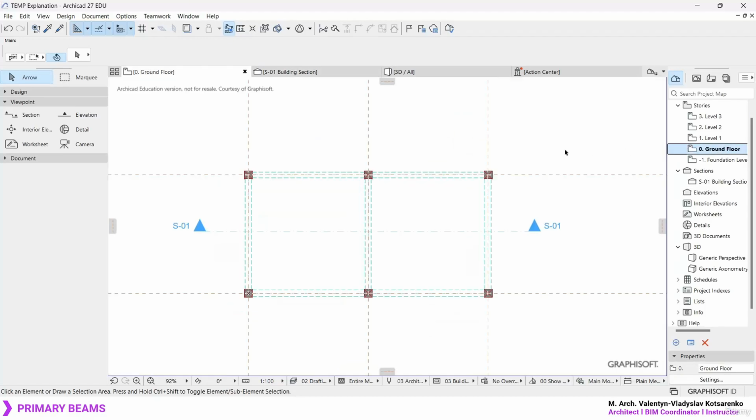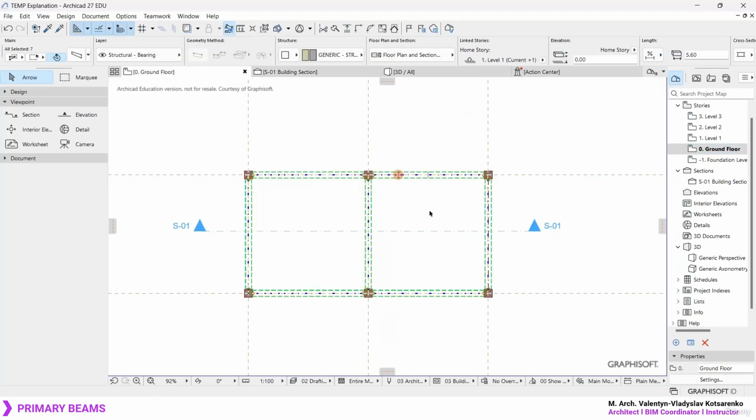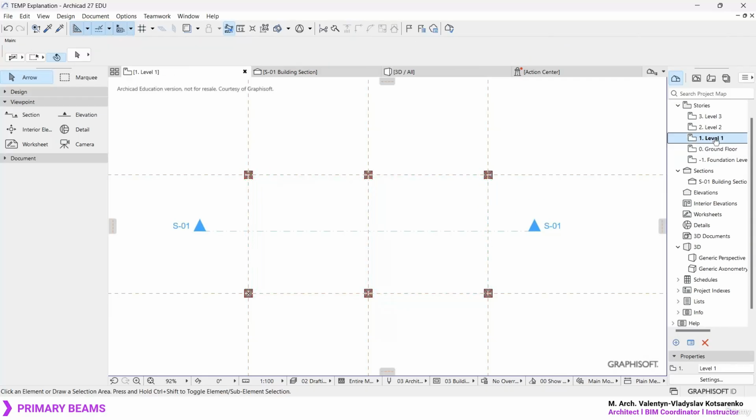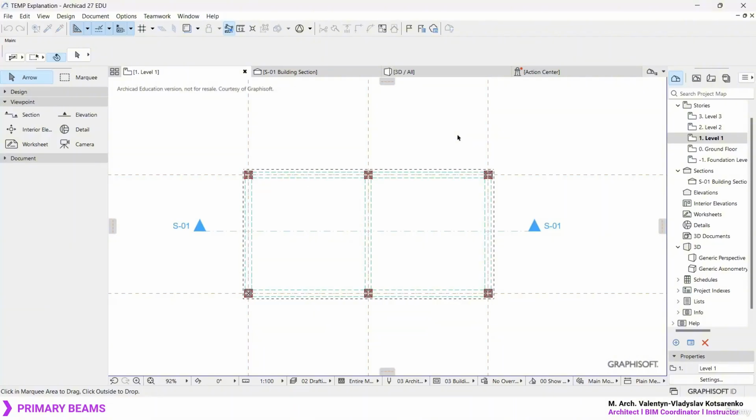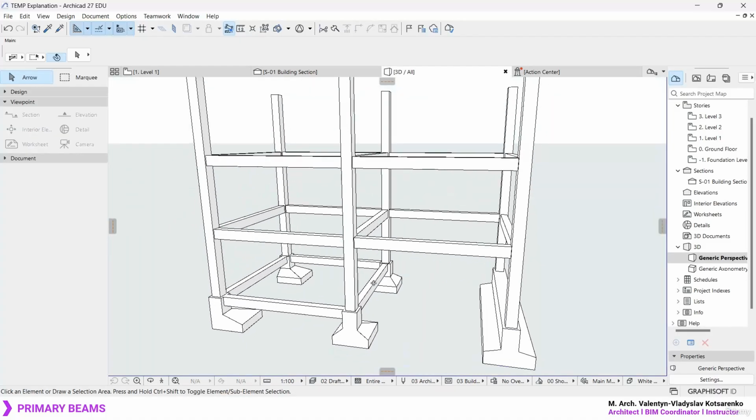So yeah, let's go ahead. Let's select the whole group. Ctrl C to copy everything. Let's switch to level 1 and Ctrl V to paste the different structures we got over here. Keep in mind, you need to position the mouse outside the marquee or the preview marquee and press Enter in order to complete the copy and paste function.